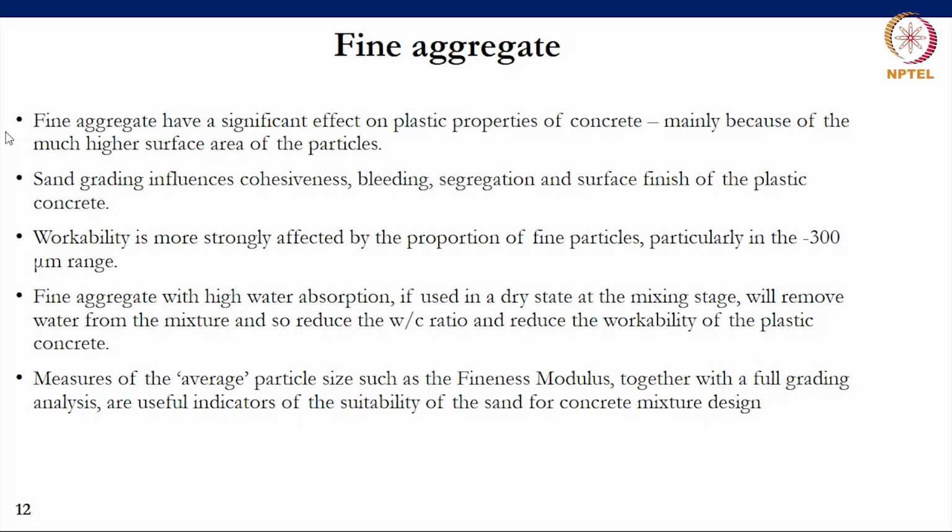Workability is most strongly affected by the proportion of fine particles, particularly the -300 micron size particles. Again, this is a factor of surface area. Fine aggregate with a high water absorption, if used in a dry state after mixing, will remove water from the mixture, so reduce the water cement ratio and also reduce the workability of the plastic concrete. So do pay attention to water absorption, and I will make reference to this a little later in talking about the hardened properties of concrete.